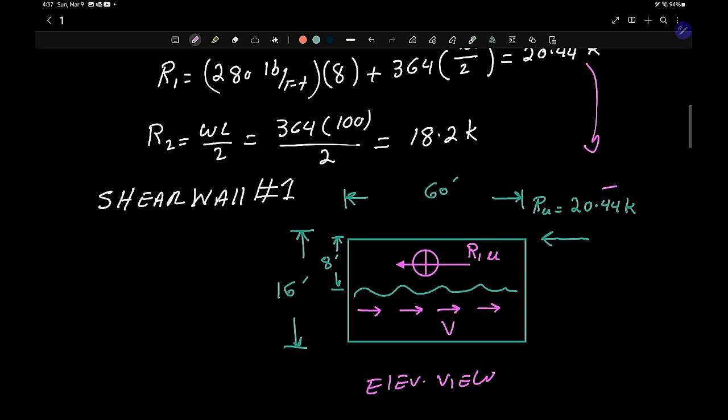This is basically using dynamic theory, which I'm not really fond of. If I had to do this, I would calculate the entire wall rather than half of the wall. But a lot of designers, the older generation like myself, use the half of the wall. The newer designers, who are more economical, basically follow the code and use half of the wall.